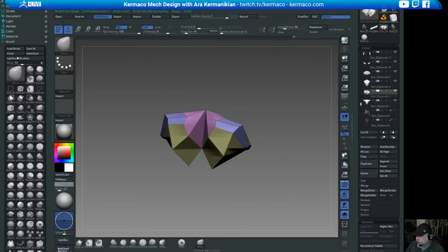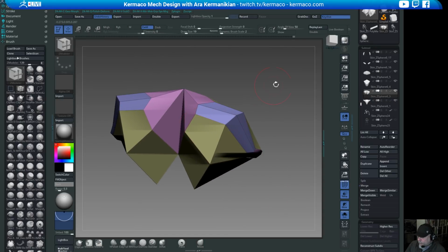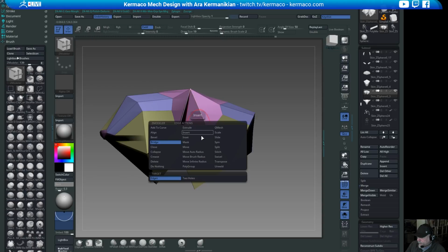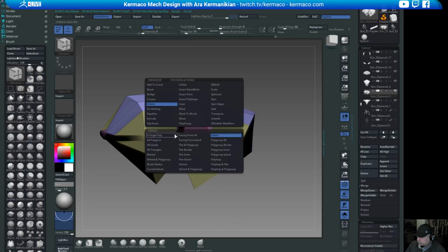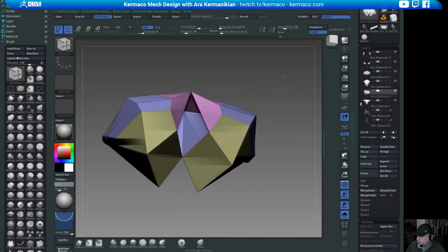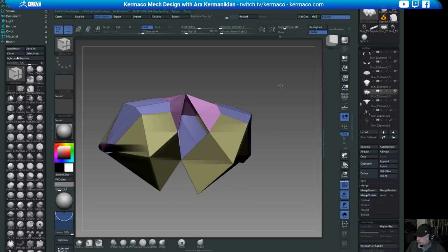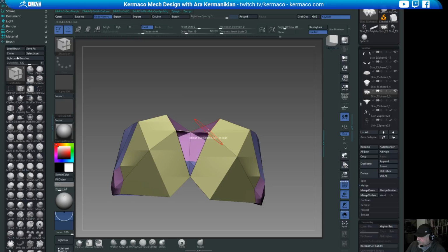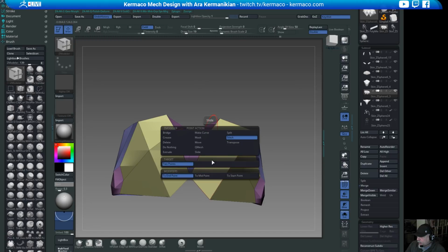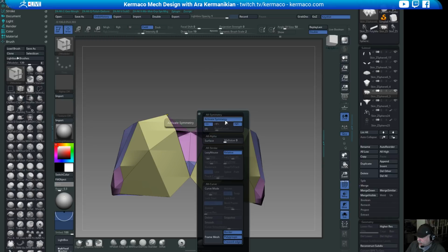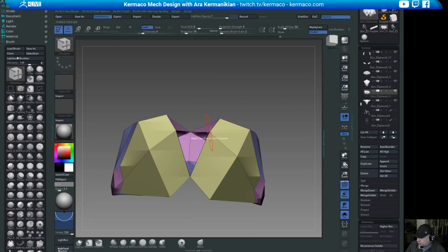So again, here I'm just going to go into ZModeler and delete these two faces. Delete single poly, 1, 2, turn double on, and what I want to do is close this up. And I wonder if I'm going to do the stitch again, but I'm going to stitch to midpoint. So I'm going to turn off symmetry here. I'm going to select this point and this one.